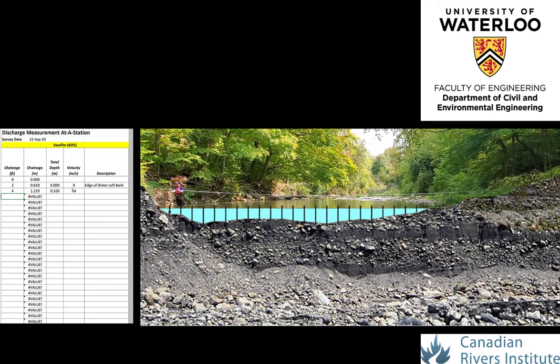At this particular vertical location, a detectable velocity was not measured, although there was sufficient depth to acquire a measurement. Hence, the velocity here was insufficient to generate the minimum force required to spin the velocity impeller. So here, the velocity is assigned the code ND, which denotes that no detectable velocity was measured.